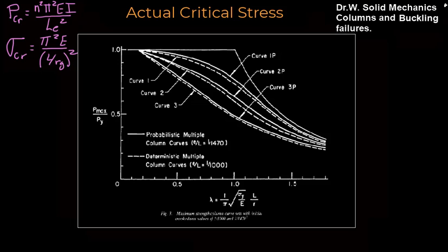And we can see here where there's a slight amount of bow in the column before they load it, and the amount of bow will dramatically change the buckling stress allowance. And again, here's our sigma yield intersecting with the Euler curve out here. So we do need some correcting factors for this.